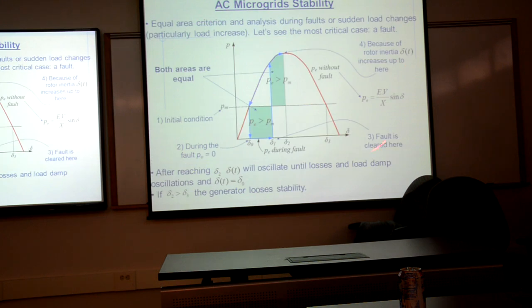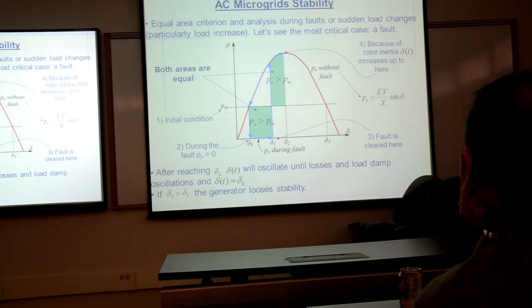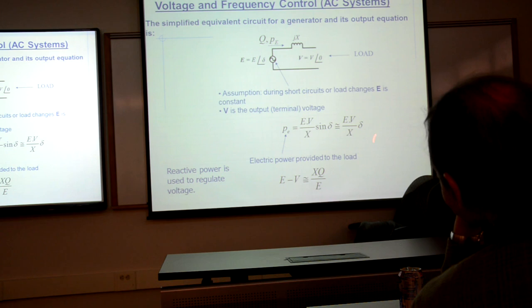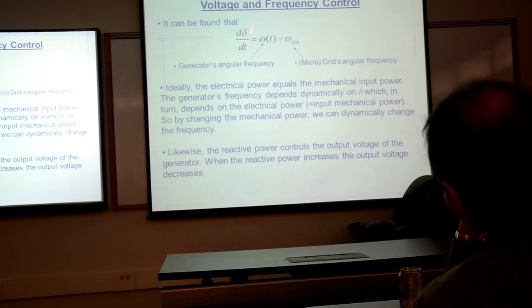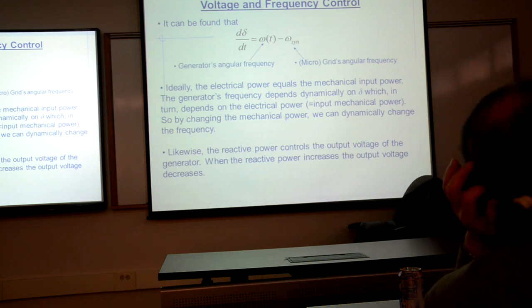And that is an example of how we build a stability analysis for that. So we keep track of the torque angle, we adjust it, and we can re-establish the active power at the level needed after a big event, for example a fault, or a sudden increase or change in the load demand, especially an increase. That is actually a simplified version of the equation. Most often used is this equation, with the torque angle and the actual speed of the generator, and here is the synchronous speed.